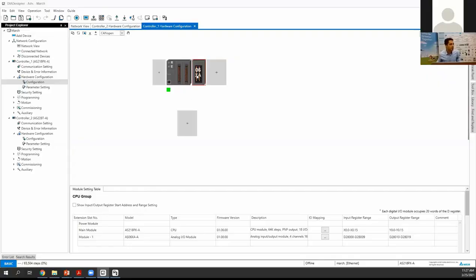So that's why we have XA. So what we want to do, we want to use the PLC analog output and read that analog output from the module input. That's the idea. So what we need, first we need to understand how we can use the built-in analog output.